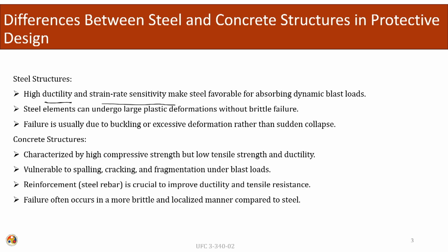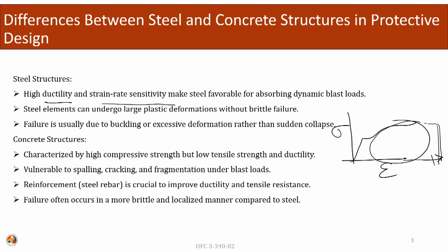Due to all these quantities, we have already seen that the area under the stress strain curve for steel is large. Since this area is large, it can absorb large dynamic blast loading. Steel elements can undergo large plastic deformation. The total deformation undergone by the steel element is large, and brittle failure does not occur in steel structures. So, it makes steel elements a favorable element for blast resistance.